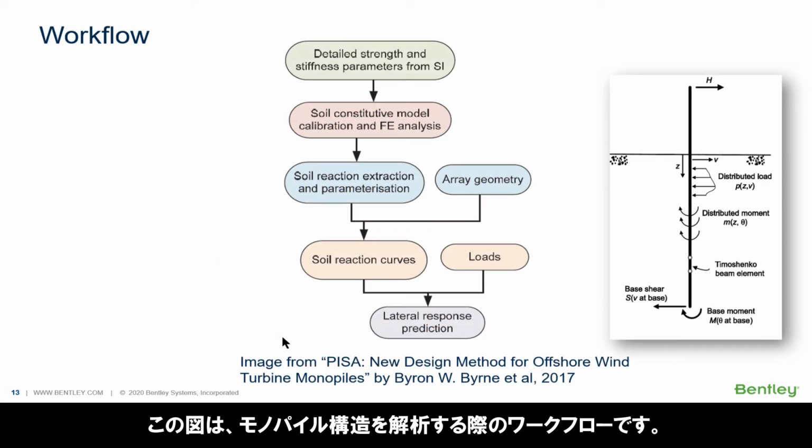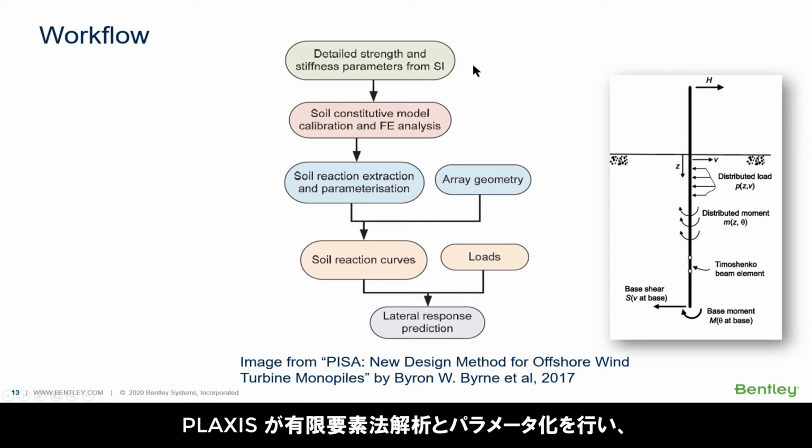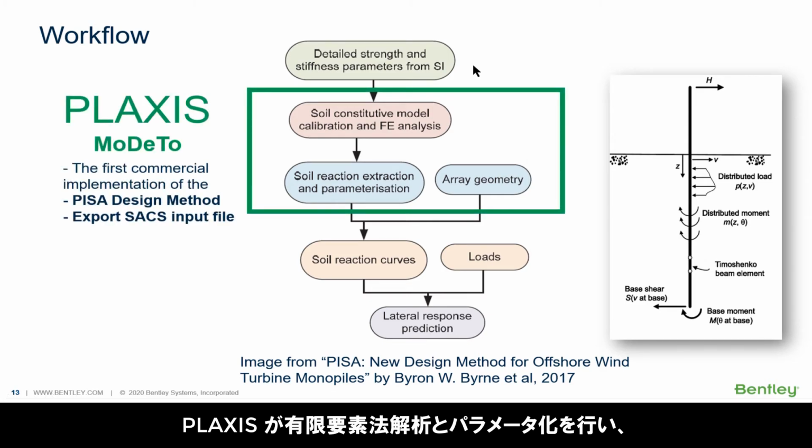The workflow here is the workflow to analyze the monopile structure. The source of the image is at the bottom. Once we are done with the site investigation, PLAXIS takes part in the 3D FEA analysis and parameterization part. Then it exports all these soil reactions in the format of SACS.